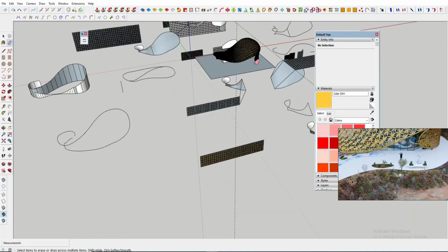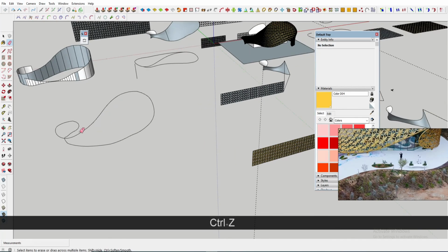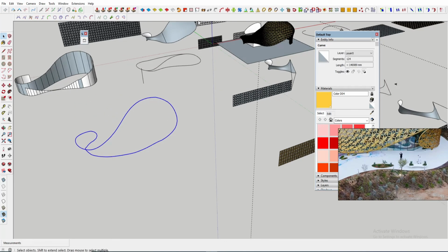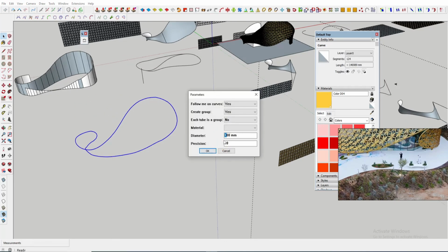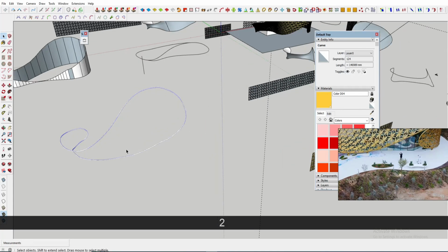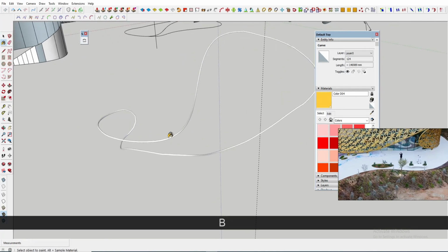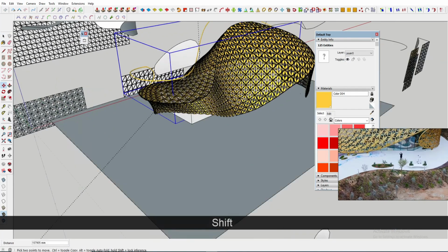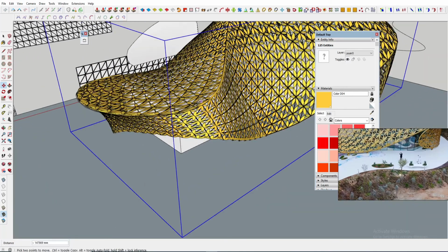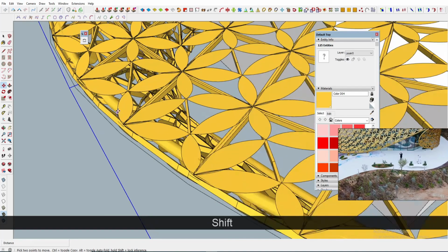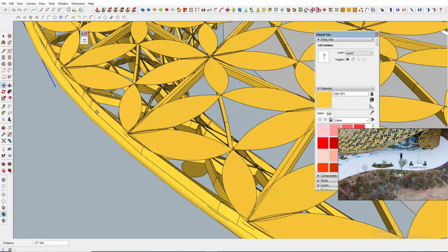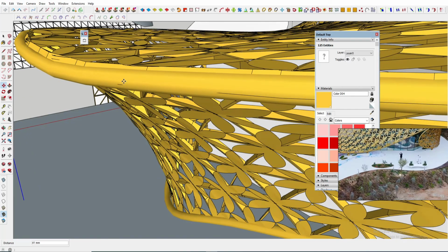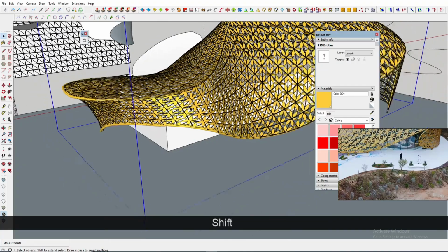So I am simply selecting all the lines and I am going to convert all the lines to be tubes. Double click, simply click the line to tube icon. So last one, diameter, you can switch the diameter. So I'm going to simply place it above in the right location. So I'm placing in the right location. That's it, friends. This is done.